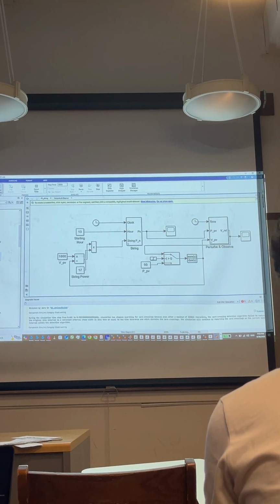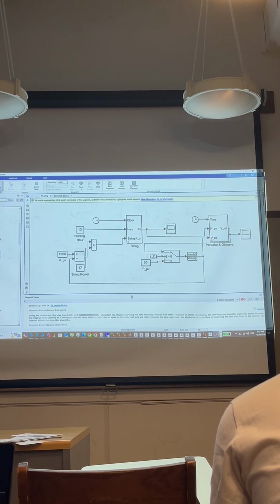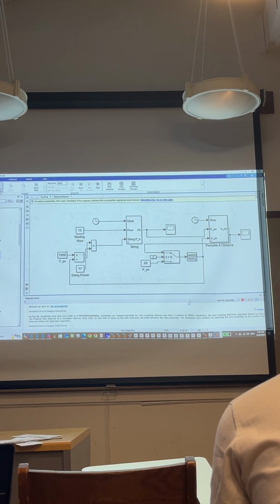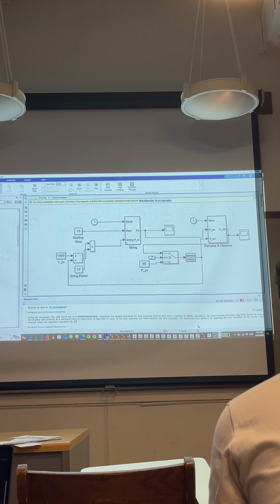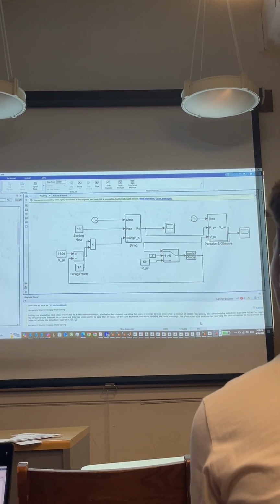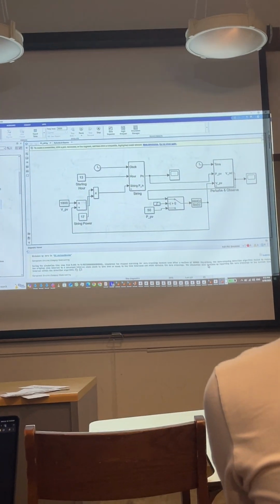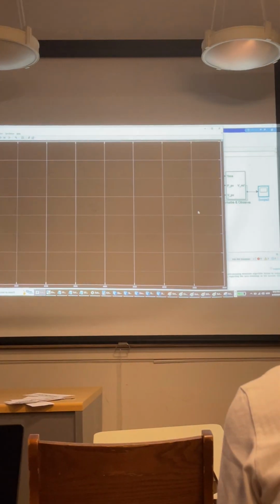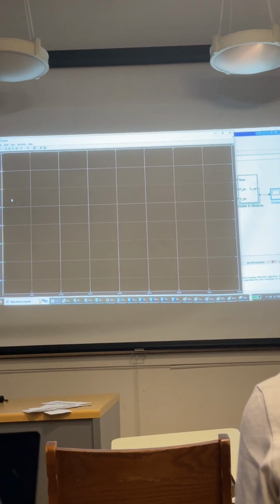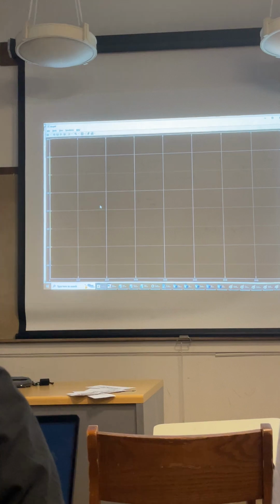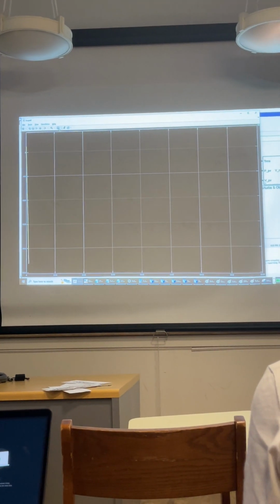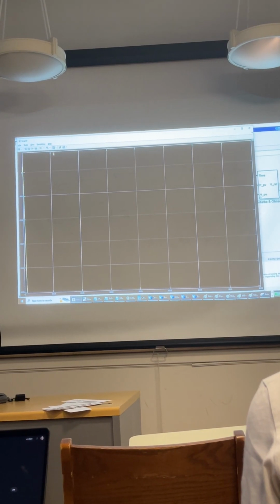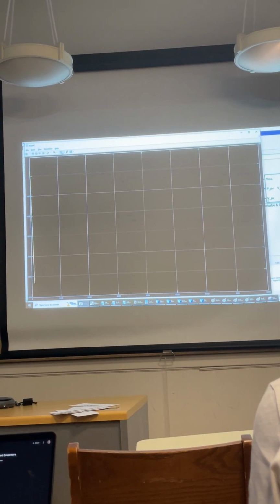Again, I have made several patches here to make the solution faster, but I'm going to explain what's happening once we get past some time. There's an accelerator also, but the accelerator might usually work opposite than what you want. There are accelerator options in the model parameters that, however, are not really accelerating the simulation. On the contrary, they're making it slower.